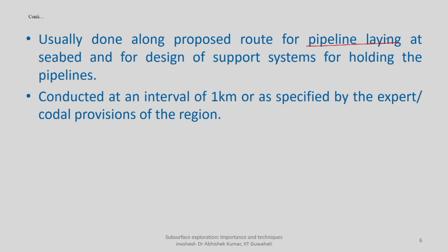As I mentioned, if your shallow geophysical investigation or geotechnical data gives you an idea that there is a possible fault along the route, then the design of the support system should be such that it can withstand any possible movement without significant settlement or any compromise on the safety of the pipeline system. That can also be a useful input from shallow geotechnical investigation.